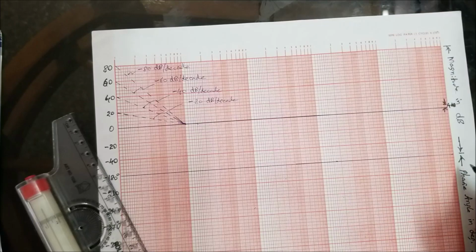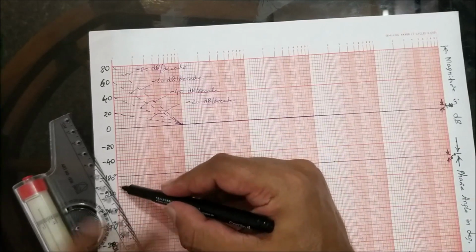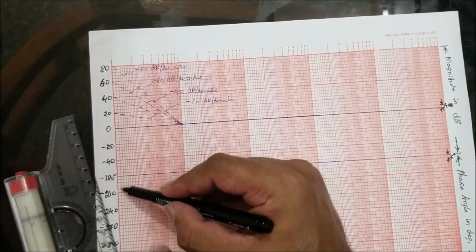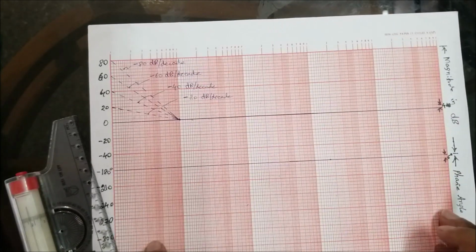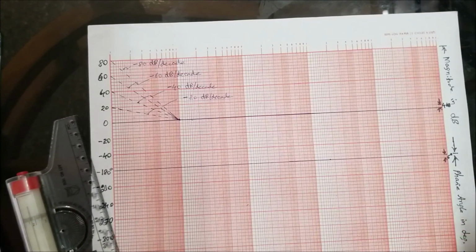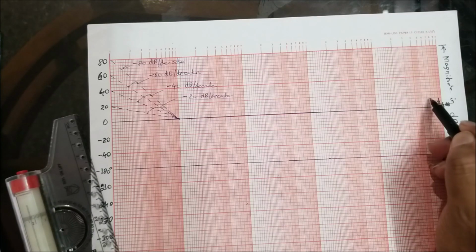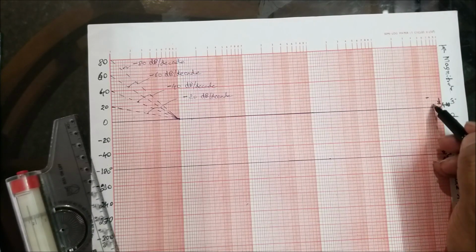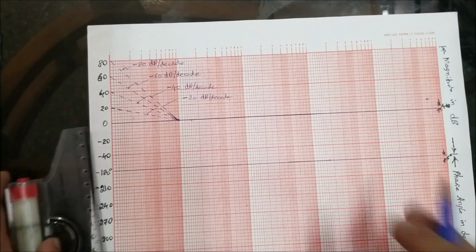Similarly for angle, the value of one line is 6 degrees, because each unit I am taking as 30 degrees for 5 lines. So one line is equivalent to 6 degrees. Now I want the shift to start the problem. The shift is 12 decibels. Each line is 4, hence I should move 3 lines upwards. That is 12: 4, 8, 12. So the shift is obtained for us.